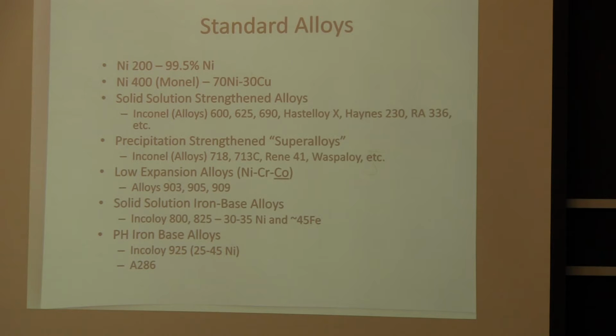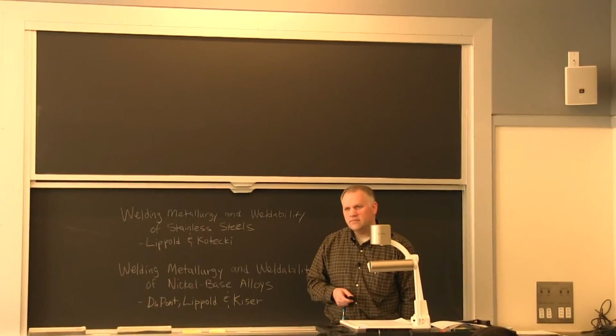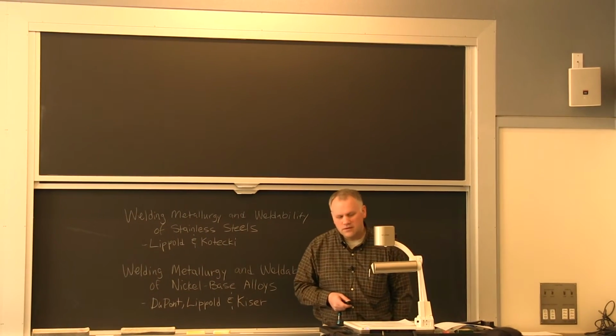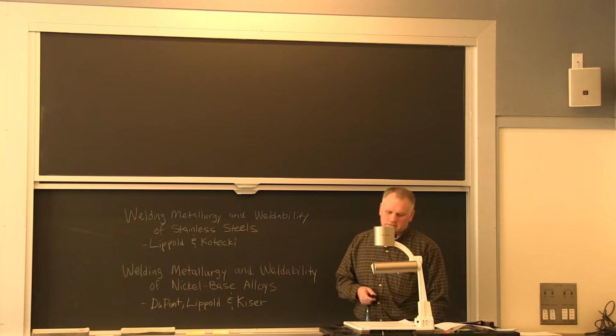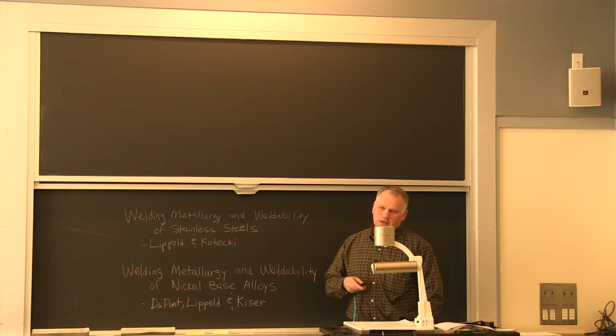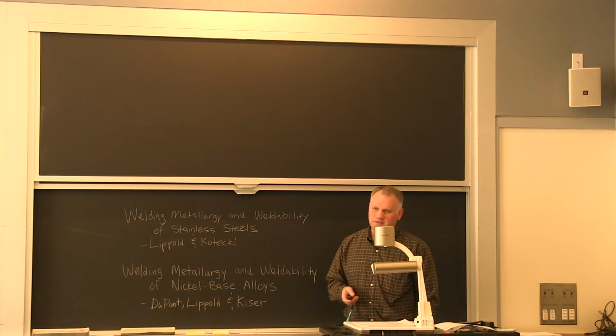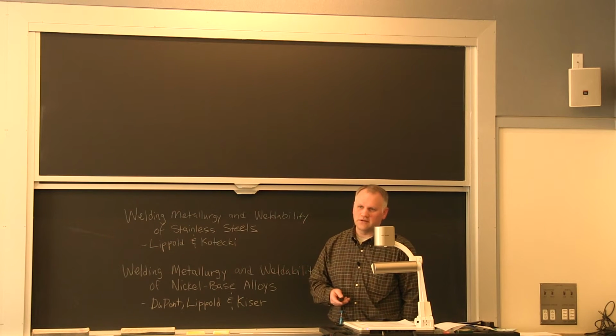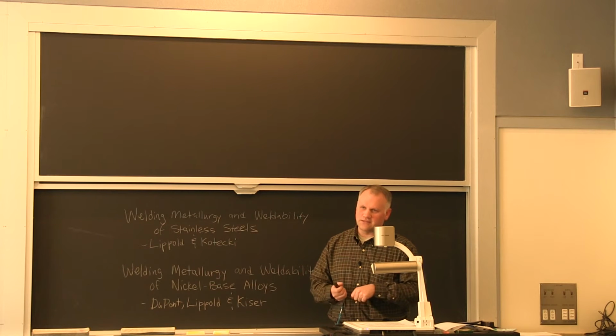Sorry, just on the previous slide for a second. You said low ductility and low toughness. Does one kind of apply to the other? Well, metallurgically, they're different terms. As far as effects, they're similar, but toughness has to do with the amount of energy that something can absorb. Ductility has to do with the type of fracture you get when it's coming apart.